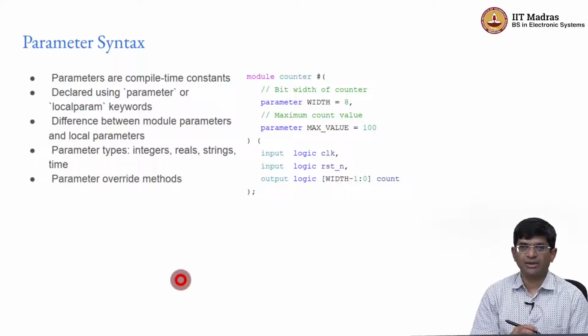Now, what that means, for example, is that certain things such as whether I am dealing with a 4-bit number, an 8-bit number or a 12-bit number have to be decided at compile time, because that literally decides how many units of hardware I am going to deal with. It is not something that I can change at runtime. Even in a language like C, such a thing could potentially have been done at runtime. I could have some way of reflecting on the code and deciding whether something should be treated as a 16-bit value or a 32-bit value at runtime. In hardware, that is simply not possible, because you have to decide how much hardware you need and build the circuit correspondingly. So, parameters in that sense are compile time constants.